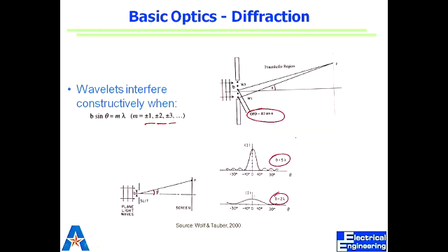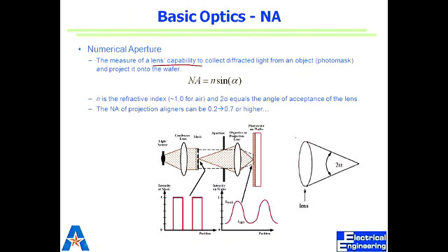So right now we are talking about photolithography, where we have these lenses, which are made of glass, and we know their optical properties and we know how to control them. We'll see what happens if we push the wavelength really down, what's going to happen to the optics. We can't use transparent optics at all. We can't use glass optics at all. And the reason is the band gap energy becomes almost the same as those wavelengths. So we'll see what happens.